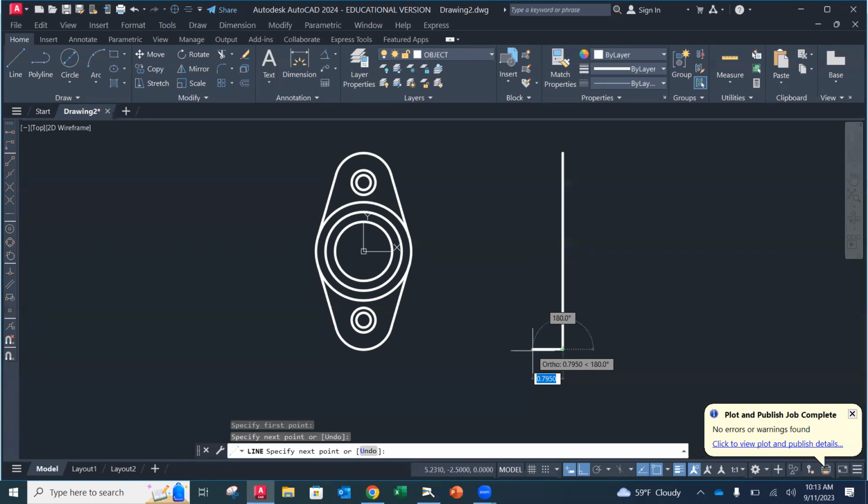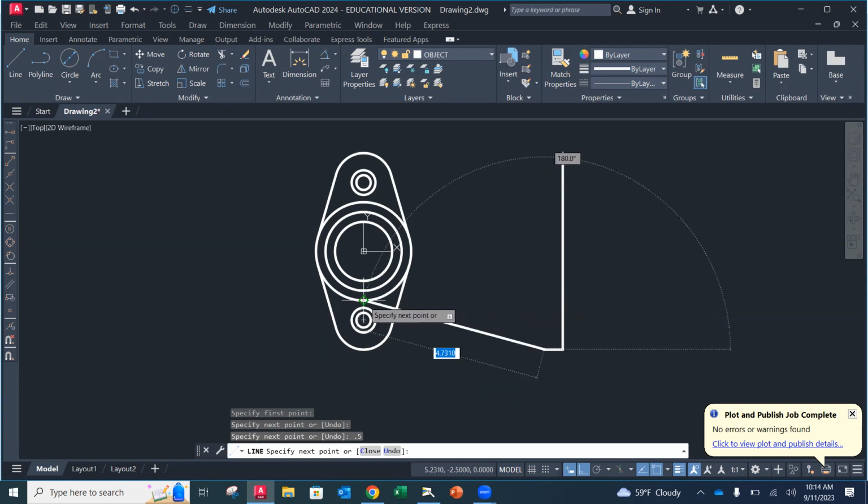Now my thickness here from the drawing, it says that I'm 0.5 thick. And now I'm going to go in. Here, I'm going to be in projection with this largest circle in that left-hand view. So I'm going to go over, activate it. There it is.